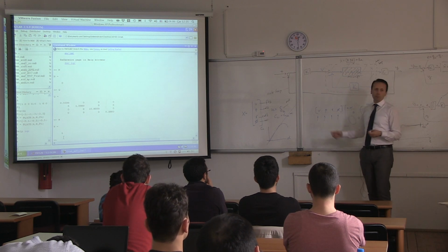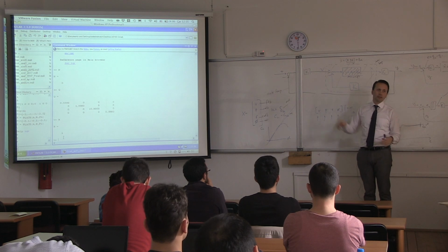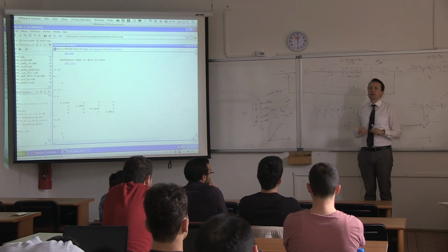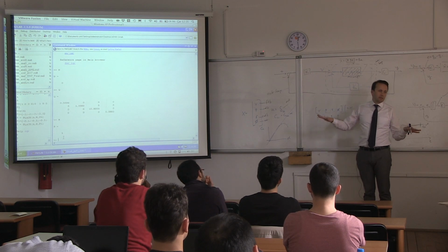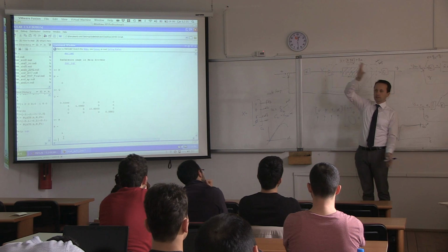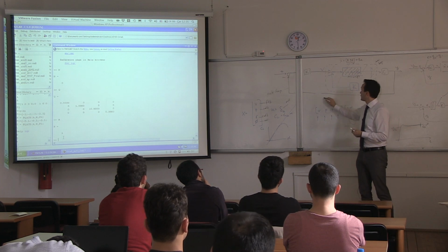Let's say, for example, just to give you an example, the p-value, the roll rate, is maximum 30 degrees per second, right? That makes sense. So in 3 seconds, you're already at 90 degrees. That would be a very high roll rate for an airplane like this. Okay? So let's say the maximum is 30 degrees per second.